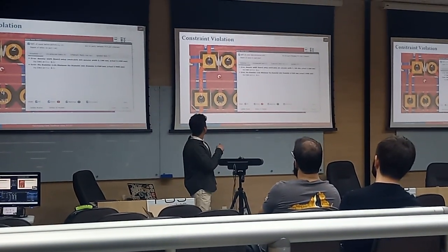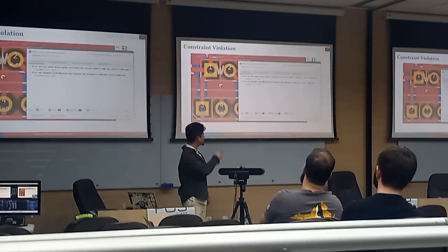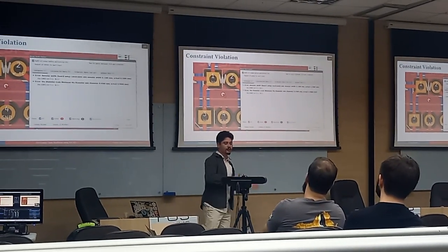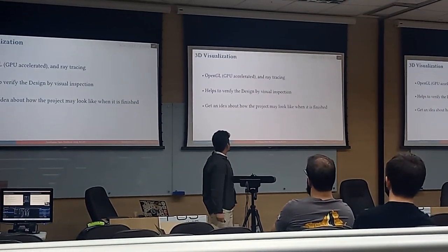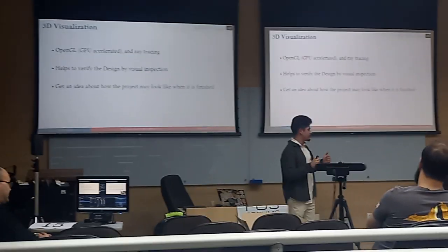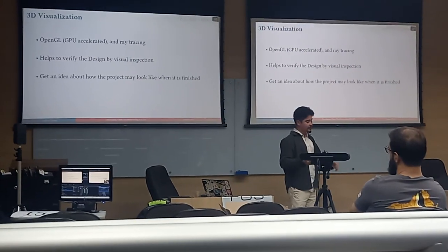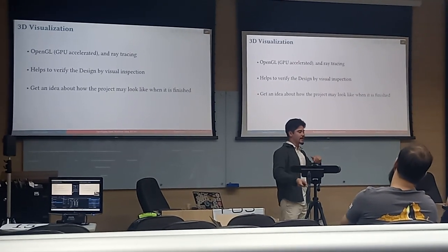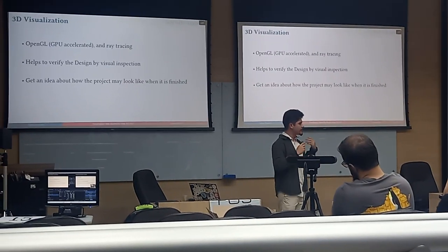And this, for example, is a constraint violation. It says the device is too small, and it explained to me what's wrong, how to correct it, and the rule related to it. So, very powerful. With all this in mind, we checked things and have a board ready to go, but I want to see the board and have an idea of my project before sending it to manufacture.